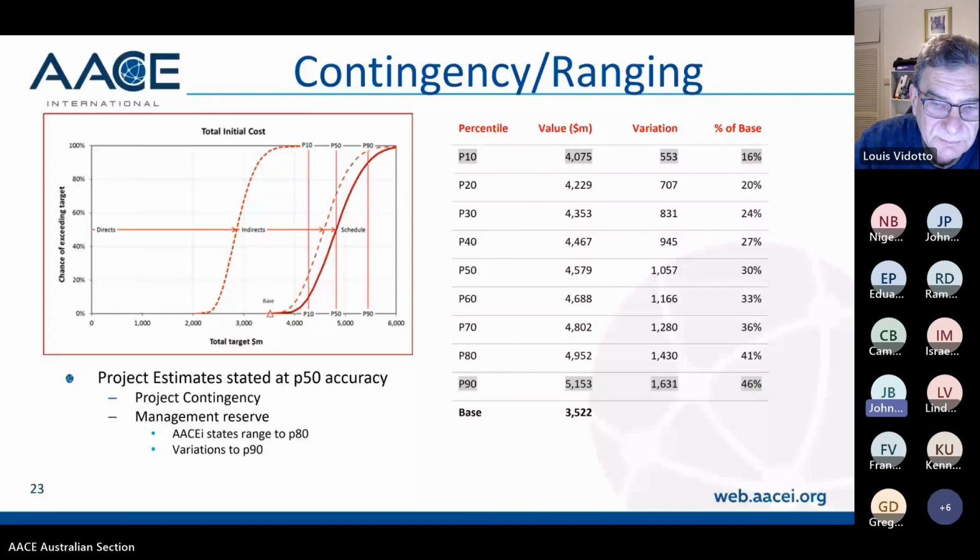That's very tight. And the only other point I wanted to make is I do like the AACE classification system, and I do use John Holman's model quite a lot. I think where that class system needs to go with the AACE is people quote percentages, but really what John's done is he's raised a good point around what those definitions are for maturity in certain aspects of a job. Like, let's talk about geotechnical data and what really should be done at various class levels. I'm trying to educate my clients to say, your gate systems really should align, and you should think about how mature those various aspects of a job should be at various gates when you're going through a class system.